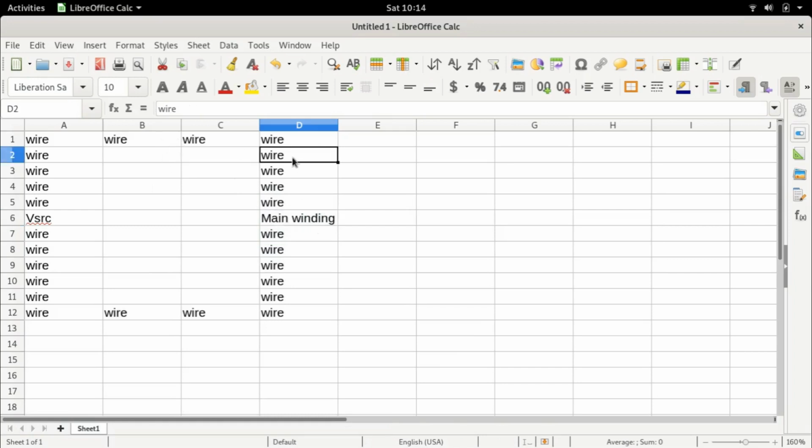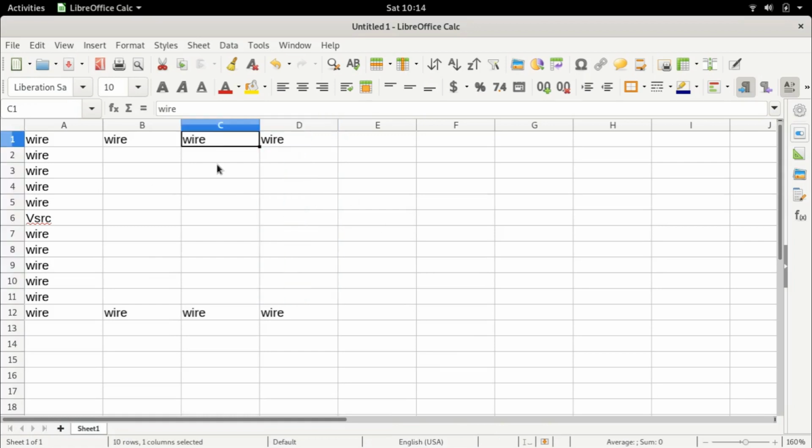components. So I'm just going to delete this, cut this out. So the very first thing you need to understand is, whenever we have a winding, we will have a winding resistance, right? That is absolutely essential. And usually this winding resistance also represents some amount of stray losses in this coil, right? Which is the stator coil. So usually I would just call this RS. RS just means it is a resistance of the stator. That is usually the terminology used.